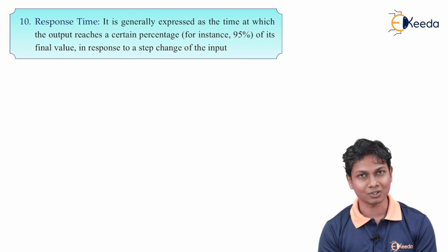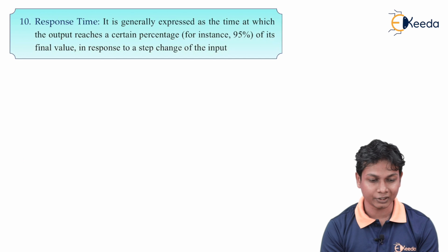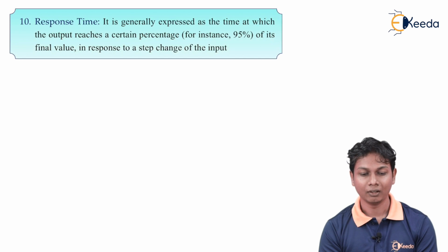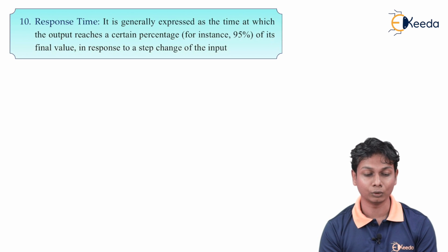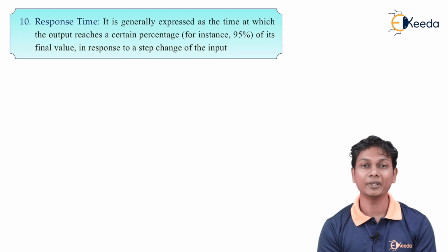Now, the response time. The response time is generally expressed as the time at which the output reaches a certain percentage, for instance 95% of its final value, in response to a step change in an input. Means what?